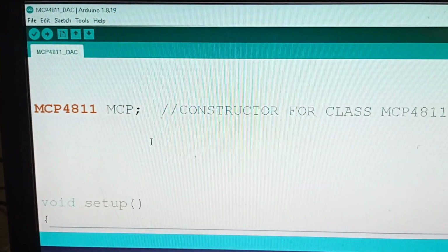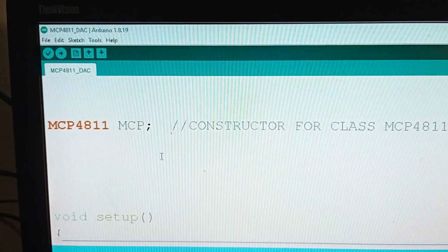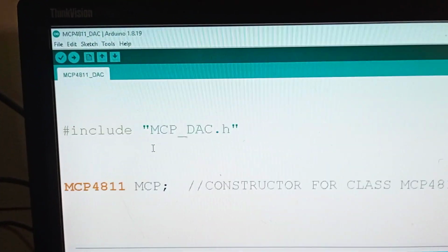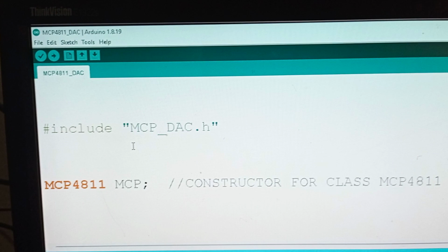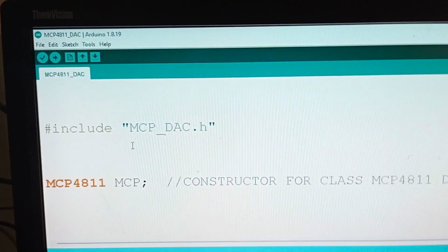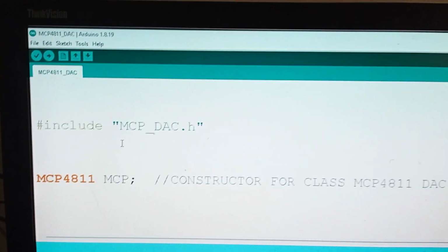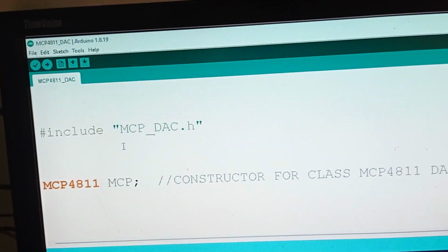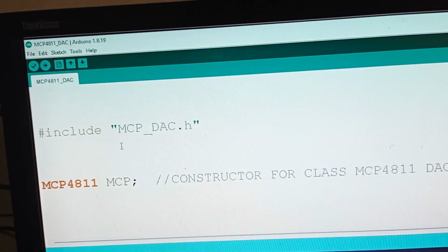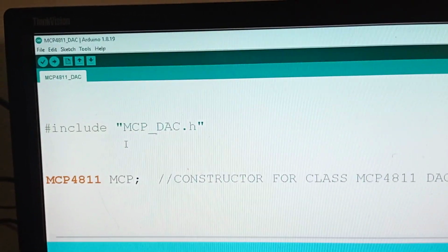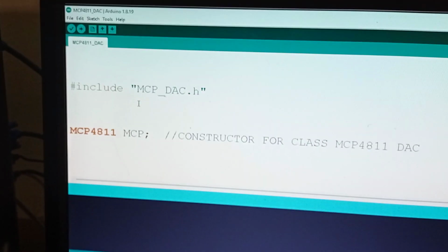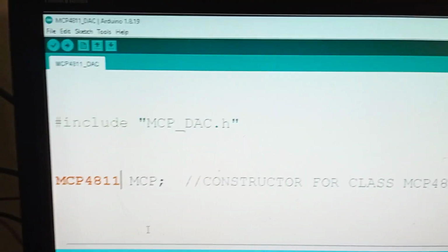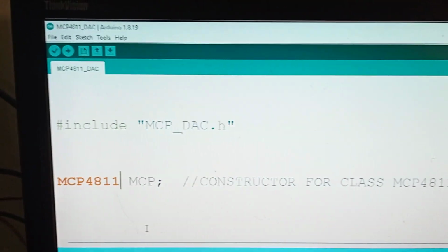You can actually generate waveforms like a triangle, square, ramp, etc. So here we are going to generate a waveform. Generally Arduino cannot produce analog outputs. We have seen the PWM. In PWM also it is still producing only 5 volts and 0. But the switching of 5 and 0 will appear as if it is giving an intermediate value. So strictly speaking, that is not analog output. So here we will be using the real analog output, which is continuously varying from 0 to the maximum 5 volts.